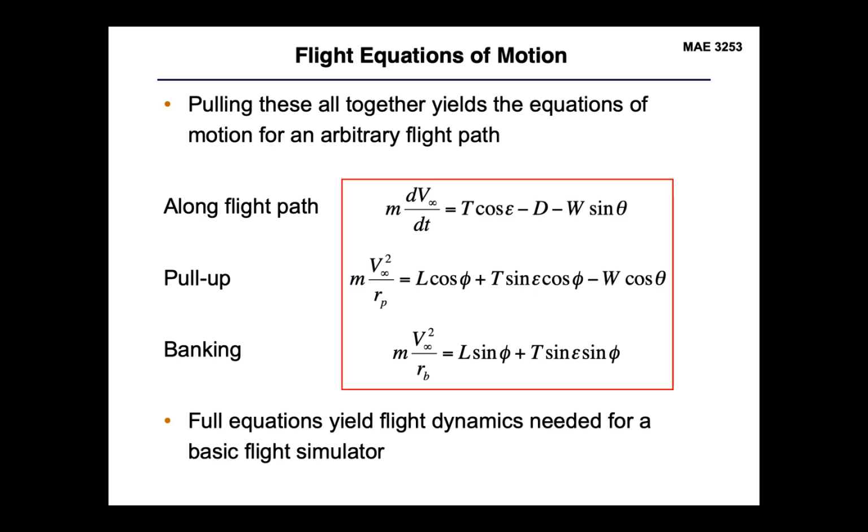So we take these, and this really then generates three equations, two for the forces acting perpendicular to the flight path, and then one acting parallel to the flight path. And then this allows us to calculate not only those unsteady forces on the left-hand side, but also determine the requirements for the forces on the right-hand side of the equation.